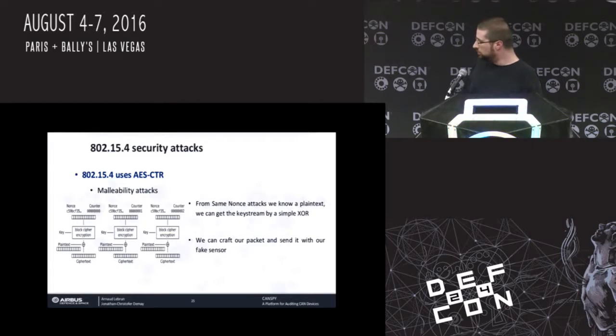The reason we were able to do so is because the supplier made 4 big mistakes that are very common. First, let me say that the usual way to work on the encryption aspect is to find a JTAG, a BDM or something to extract the firmware, and from that firmware to extract the key. But since we were not able to do that, we had to work at the encryption level.